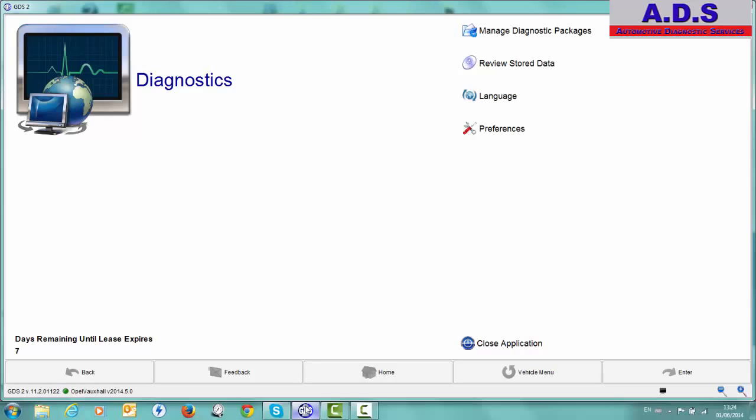Hi, today we're going to run through using the GDS2 software with the Mongoose Pro GM interface. With this interface and a low cost subscription for GDS2 software, we have full dealer level diagnostics. Note for programming, this is a separate software. You need an SPS subscription as well if you want to do programming, but you can also use it through the Mongoose lead. The GDS2 software is for the models from the launch of the Insignia and any new models